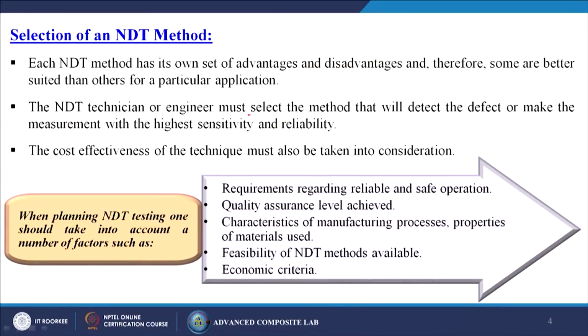So, basically each NDT method has its own set of advantages and disadvantages, and therefore, some are better suited than others for a particular application. The NDT technicians or engineer must select the method that will detect the defect or make the measurement with the highest sensitivity and reliability. Yes, of course.